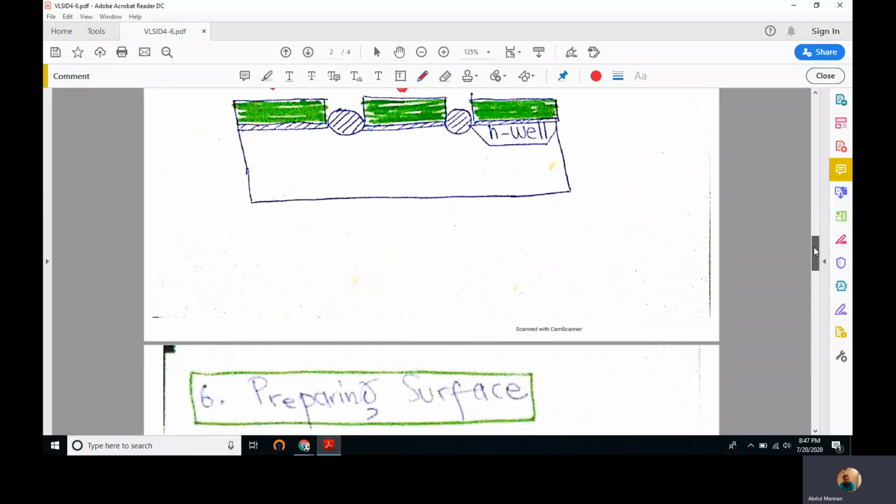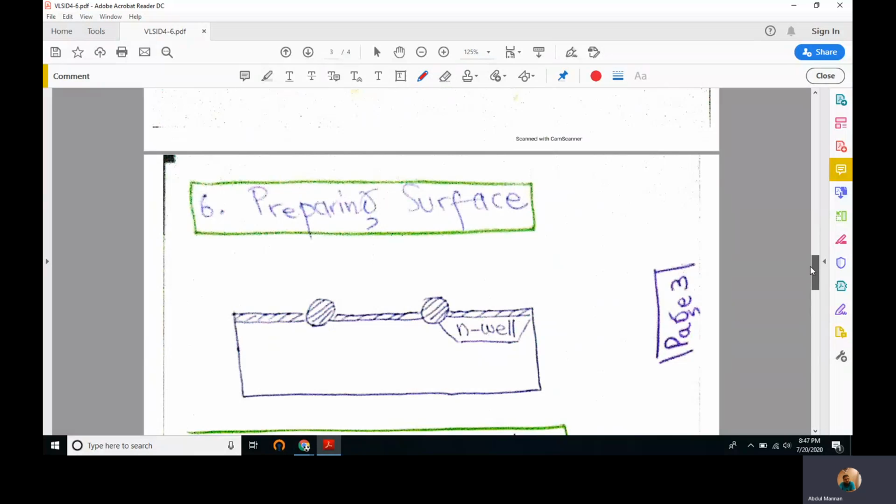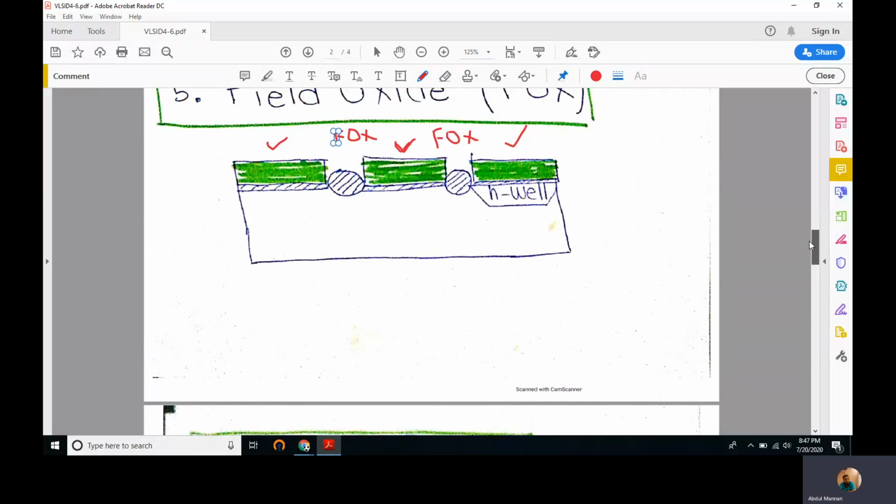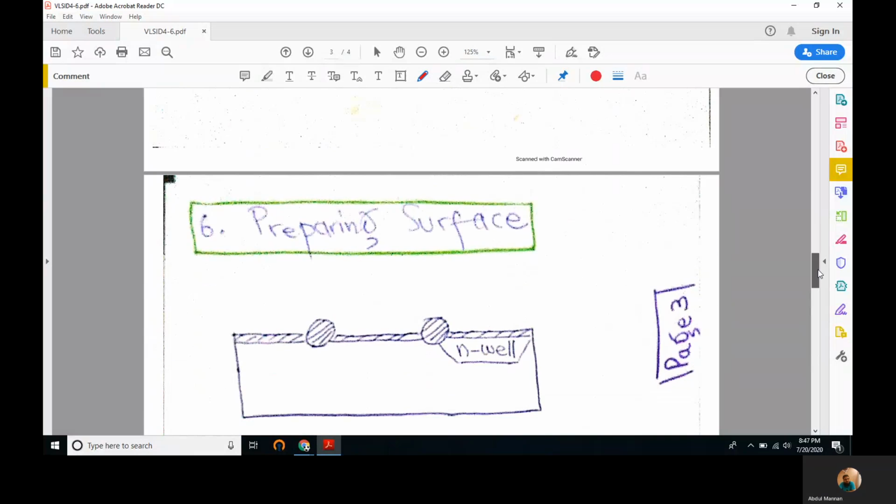Under these green shaded areas now we are ready to implement doped silicon regions, and then we'll use a chemical to remove these green hardened layers, so that now we can etch these layers and convert them into doped silicon regions.